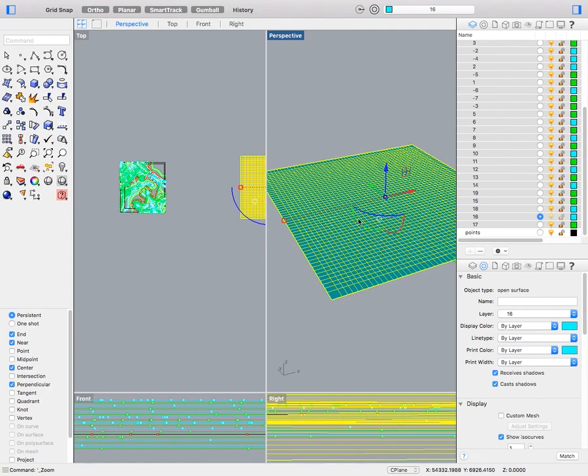Now in order to double check and see how that terrain has brought it out: Jeff's group created their model from 1 meter contours, and when that was actually built in a model, the contours were far too spaced out. So they went back in the model, and now they're trying to create smaller contours, so 1/2 meter contours.